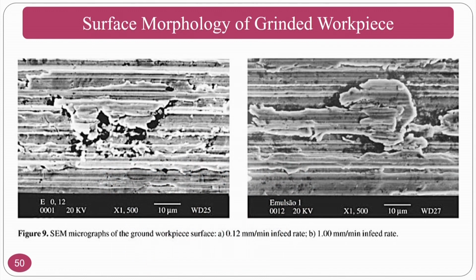The grinding surfaces, as I said, the forces are very high. Forces in grinding are very high, because of which the surface damage will be very high, and you can see the surface damage, ploughing. Okay. In the mechanism of grinding material removal, there are three mechanisms: abrasion, ploughing and rubbing.